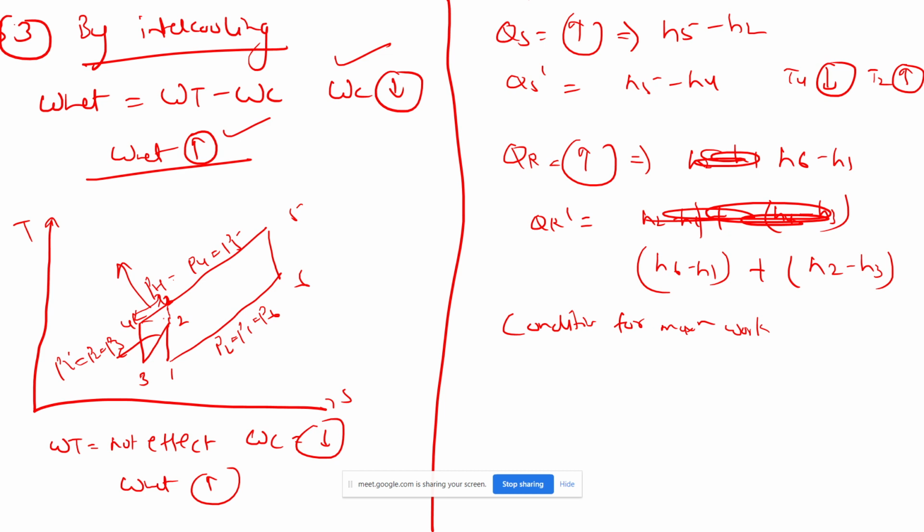We are decreasing the temperature of the gases entering the combustion chamber. That's why the compressor work is decreasing. We are not increasing that much temperature directly in one compressor. We are first compressing and then intercooling the gases coming out of the compressor and then supplying them. But it is compressing two times. Yes, it is compressing, but wait, I'll show you.